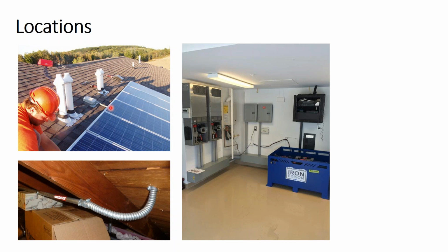And something that is not fully installed does not have the same weather rating as something that is installed. These inverters are designed to hang on a wall. You know, they could be a NEMA 3R inverter, but if it's sitting on its back on a pallet, it will not have the same weather rating as being fully installed, where maybe these conduit entry points that come from the bottom are not watertight. And so they only get that NEMA 3R resistance when the inverter is hung on the wall.